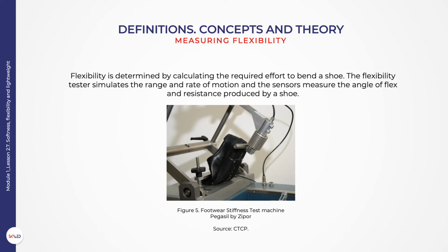For example, both dynamic longitudinal and torsional stiffness of footwear can be quantified by the use of Sauter's STM507 dynamic footwear stiffness test machine, which measures the force required to flex a shoe and the angle to which that shoe can be flexed comfortably. The result of the test is a stiffness index, which can be related to wearer performance and wearer expectations. A low stiffness index indicates a high level of footwear flexibility.